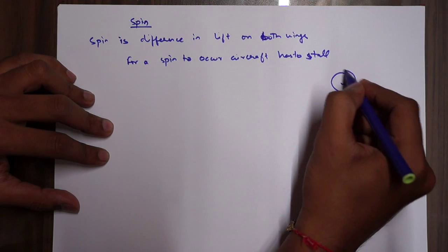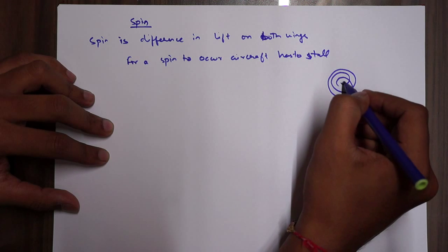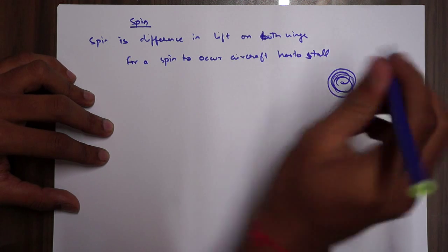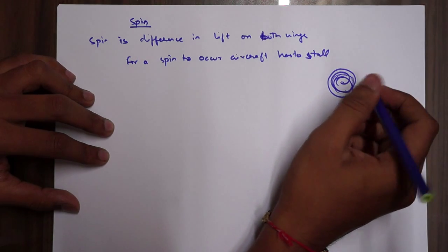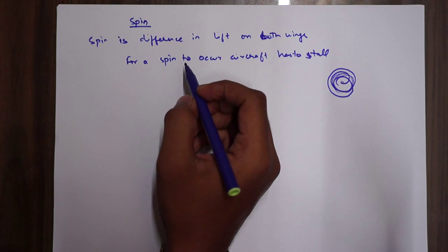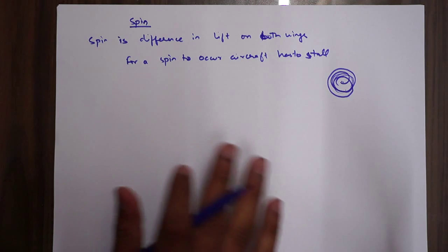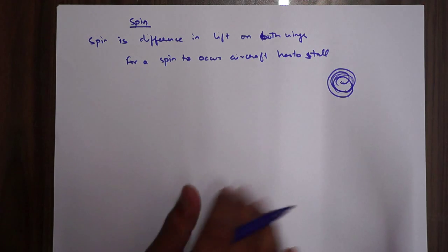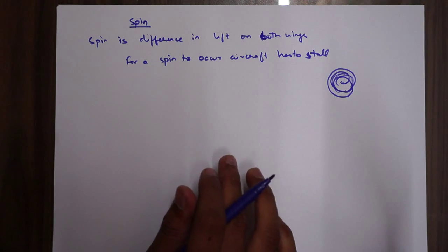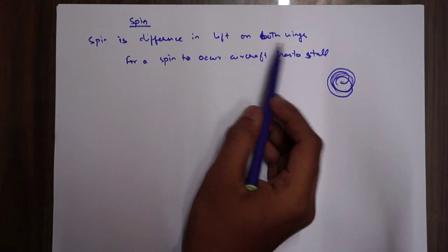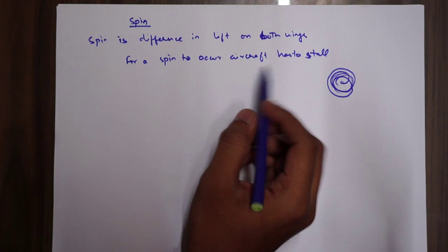something like this, into a vertical axis, and will keep rotating the aircraft like this and descending rapidly. And this spin will happen when the wing drops on either side. Say on the left side the wing drops, the nose will tend into the spin and the spin will be initiated. So there's a differential lift on both the wings, and the spin occurs.